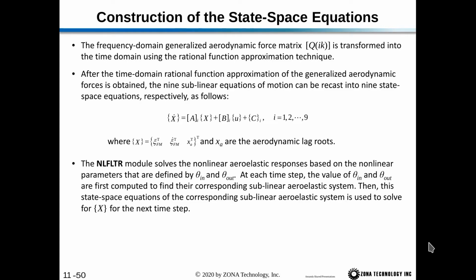Now the nonlinear flutter module solves the nonlinear aeroelastic responses based on the nonlinear parameters that are defined by theta in and theta out. At each time step, the values of theta in and theta out are first computed to find their corresponding sublinear aeroelastic system. Then, the state space equation of the corresponding sublinear aeroelastic system is used to solve for x for the next time step.